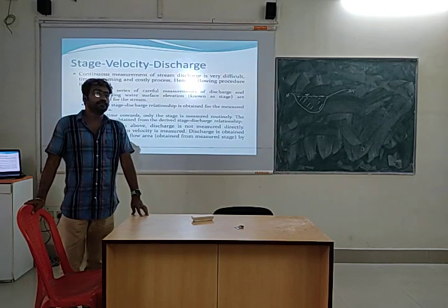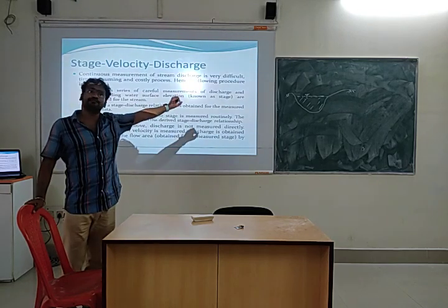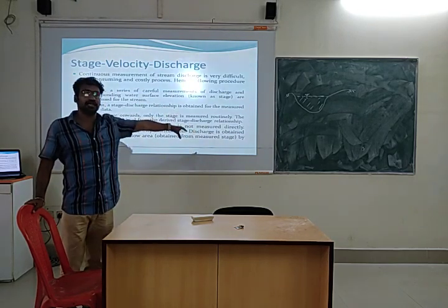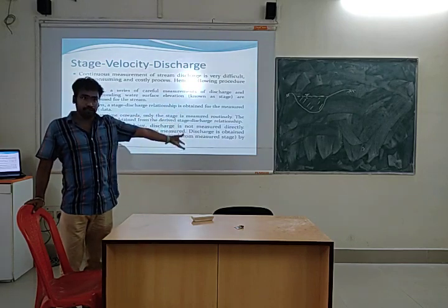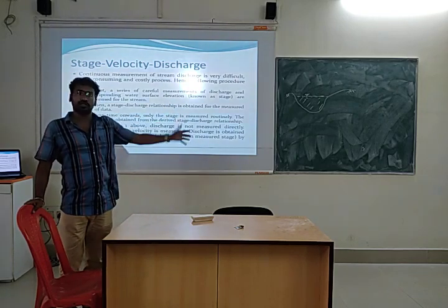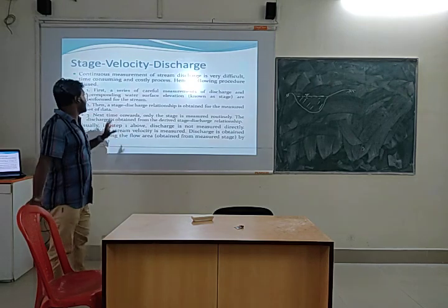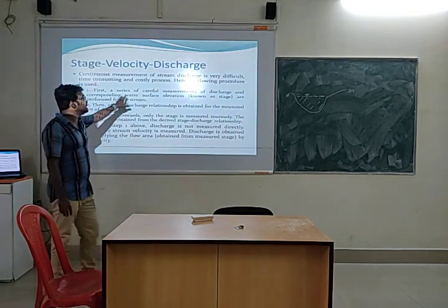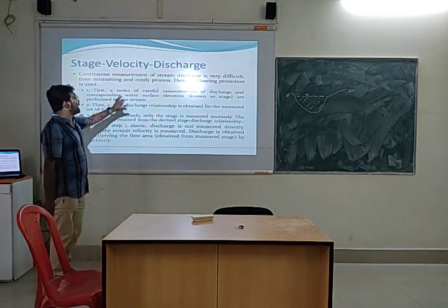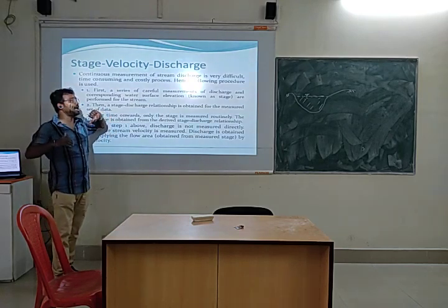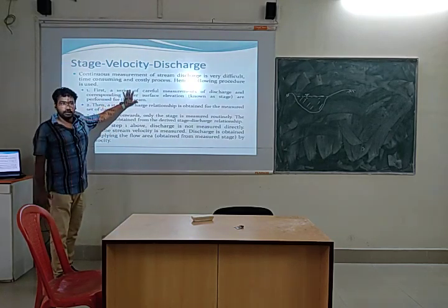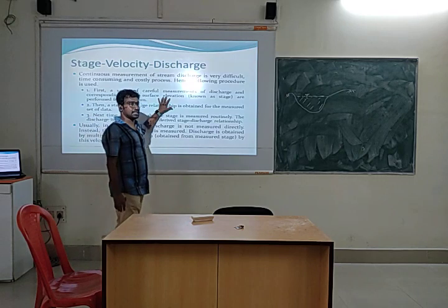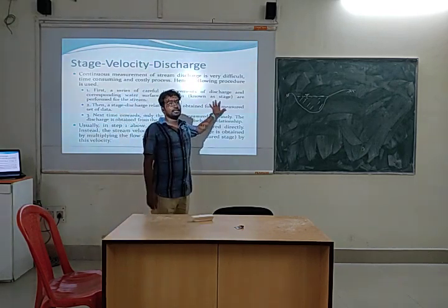But the main dependency will be the elevation, because if elevation changes, cross sectional area will change, volume will change, so discharge will change. So we can find out some relation between this discharge and elevation in various time series. This surface elevation will be called as stage.